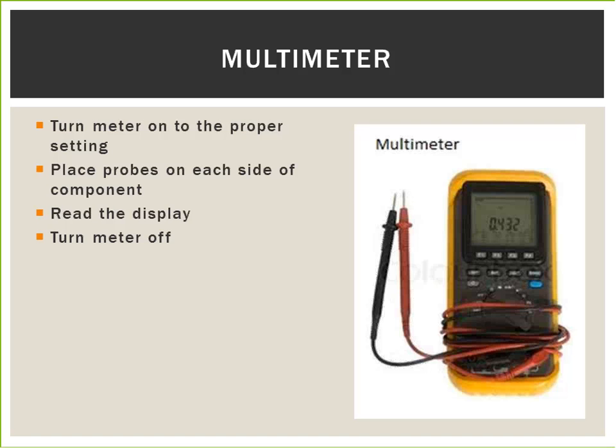Instructions include: first, turn on the multimeter and connect the probes if necessary. The negative probe is black and the positive will be red. For some applications, this is important, while for others, it does not matter. Use the probes to measure resistance by placing one on each side of the component to be measured. For this function, the probes are interchangeable.